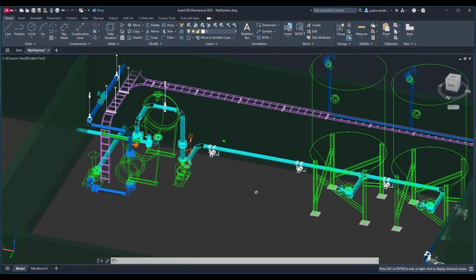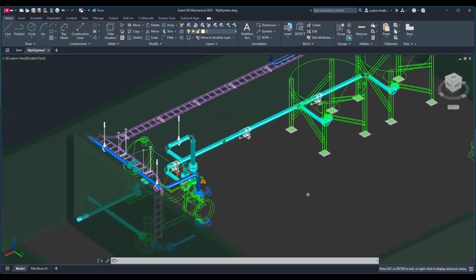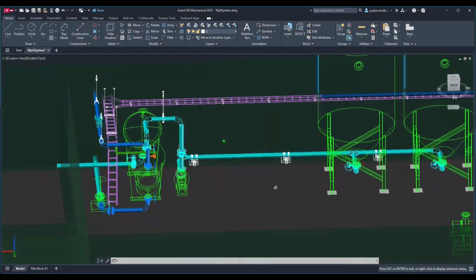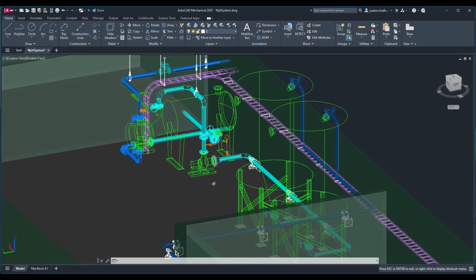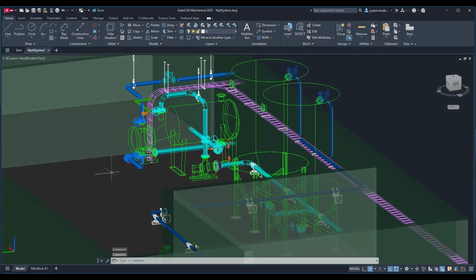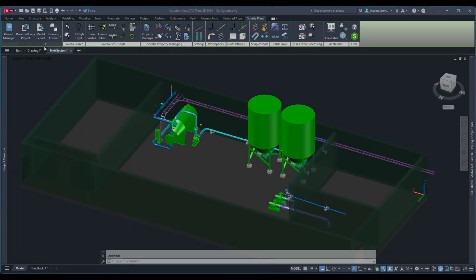Here we can see an example of a drawing open in AutoCAD Mechanical from Plant 3D not exported the correct way. To work around this issue, we need to export our models as 3D solids. There are a few ways you can do this in standard Plant 3D, but it is time consuming. This is where our model export tool comes in handy.